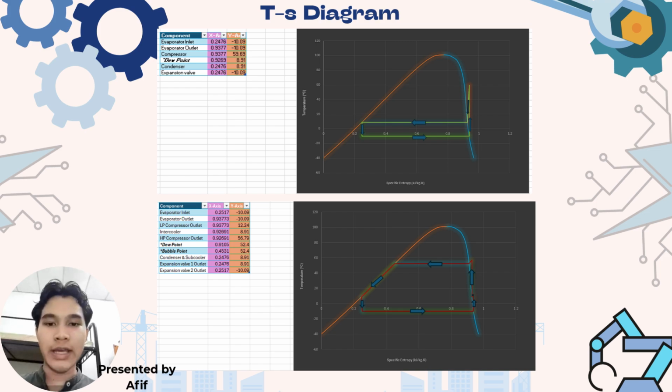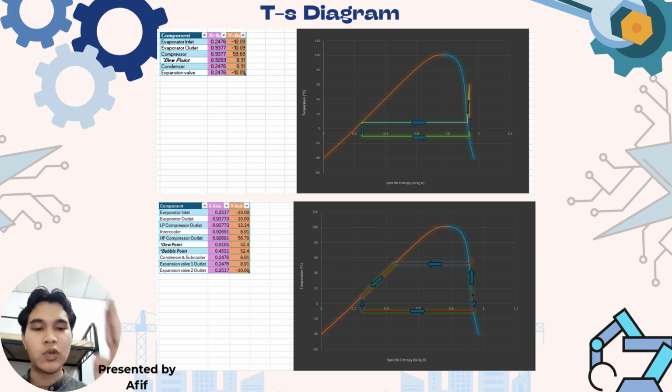So using the values obtained, these are the TS diagrams for the unmodified and modified refrigeration cycle of our project. The first one is the unmodified version. As we can see, the first horizontal line from the bottom represents the evaporator, and then the second state, which is after the compression part, is represented by the vertical line going upward straight to the superheated region, and then it continues entering the saturation line, becoming a saturated liquid-vapor mixture, representing the condenser, followed by the expansion valve, and it recycles back to the evaporator.